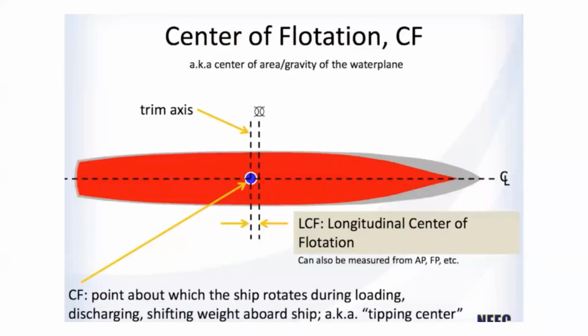What happens to the LCF? Well, the water plane will change, right? The ship will ride lower in the water. So the waterline changes, and the water plane shape will change because it's not a uniform hull. So the LCF will change accordingly. The LCF depends on your water plane, but the center of mass doesn't.